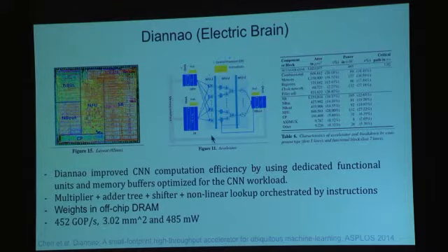So it has 16-bit integer multipliers, 16 of them, and then a summing tree to produce the one activation. It has relatively small buffers for the weights and the activations, and a small output activation buffer. So it requires going out to DRAM to fetch everything, but if you're batching, it can get a certain amount of reuse out of this.